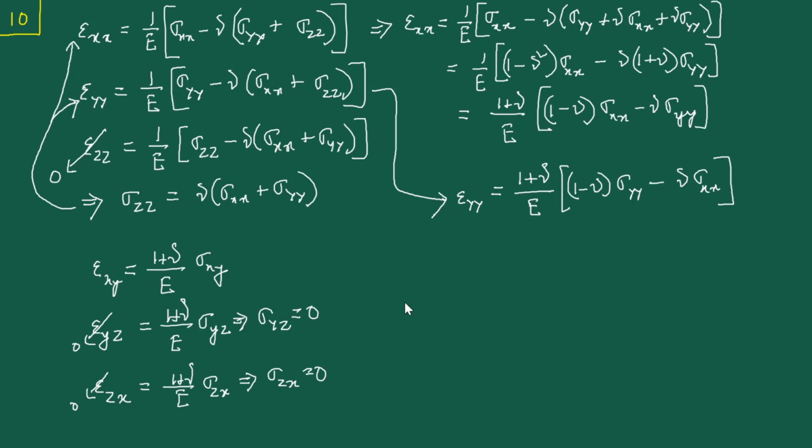We motivated the entire discussion surrounding the Airy stress function by considering the stress equilibrium equations, definitely, but it was only much later, after we had considered the compatibility equations, that we actually incorporated the information from the stress equilibrium equations, and that is exactly the route that we'll follow now. After we have considered the constitutive equations on this page, we are going to consider the compatibility equations.